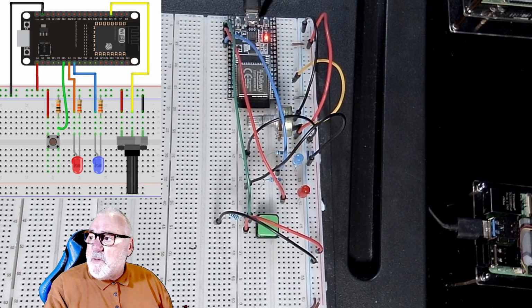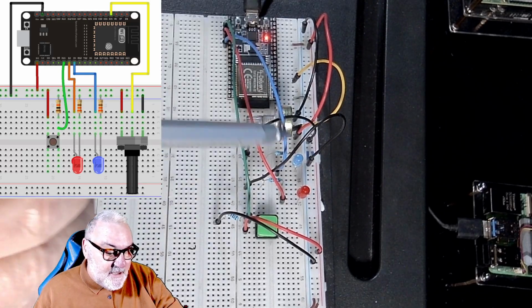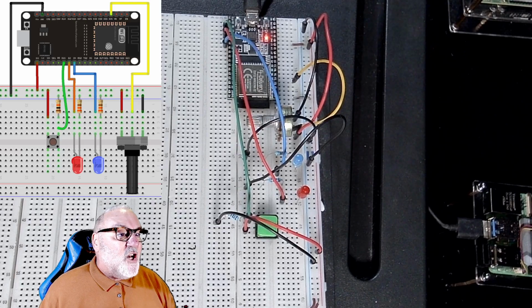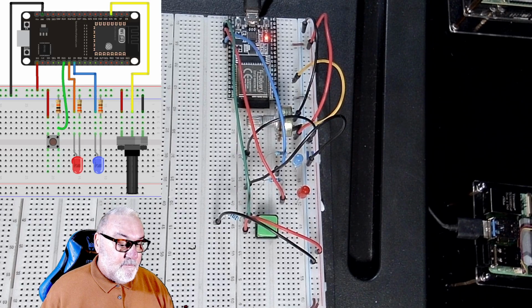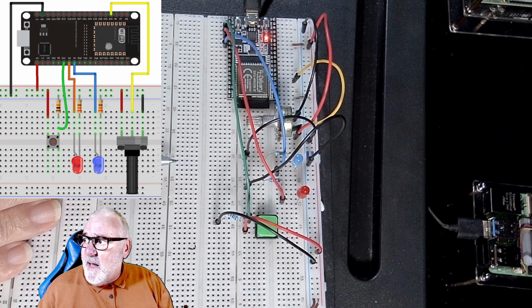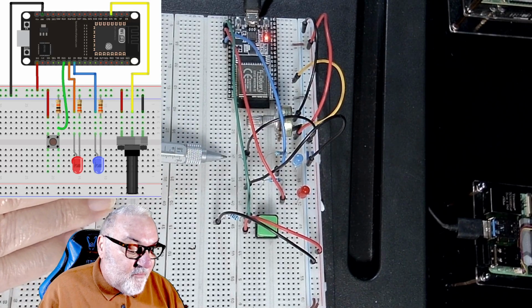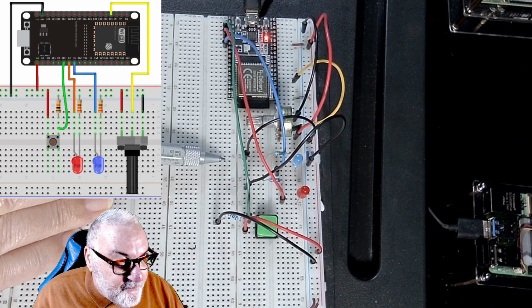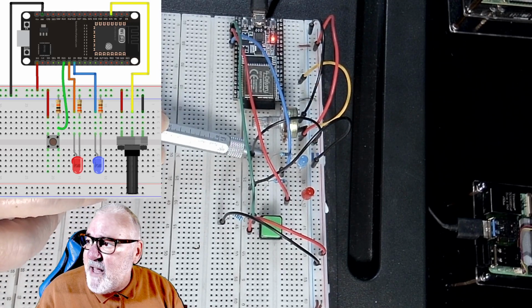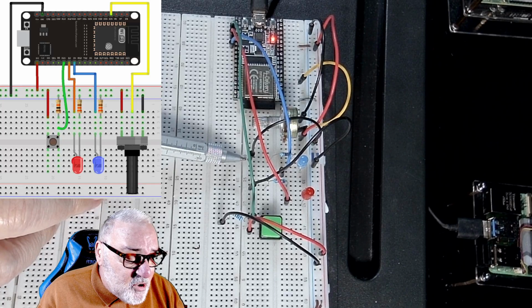That's the potentiometer. We've then got the 2 LEDs. Both long legs of the LEDs go to the right. Then the short leg goes through a 220 ohm resistor across the trench, and from there to ground.